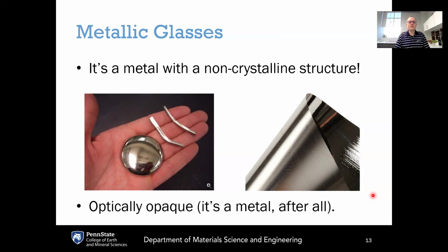But if you were to make alloys that have enough different metallic elements in them with different types of crystal structures that they prefer, one can leverage the alloy's inability to form a single crystal in order to stabilize these metallic alloys in the glassy state.